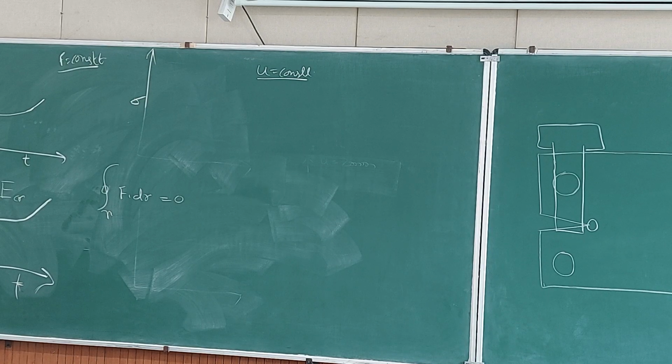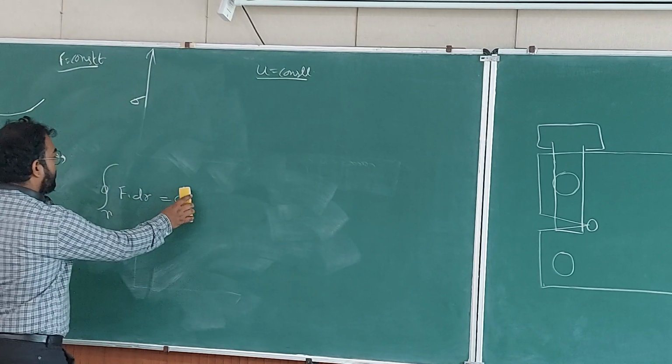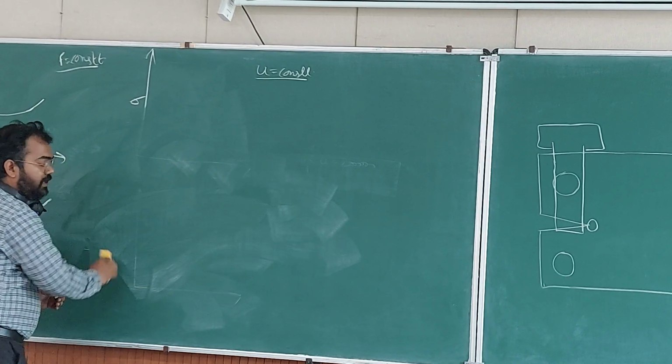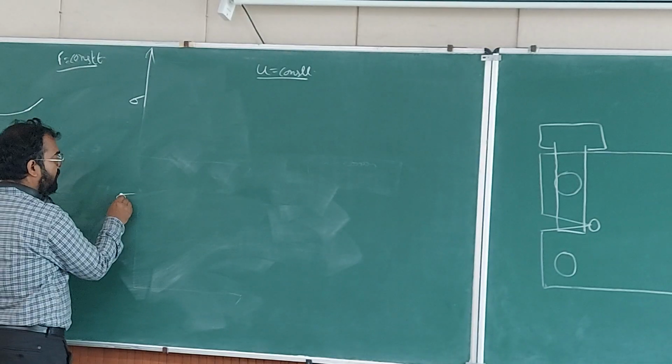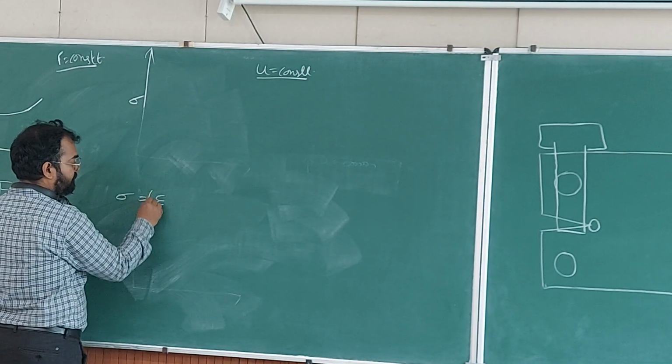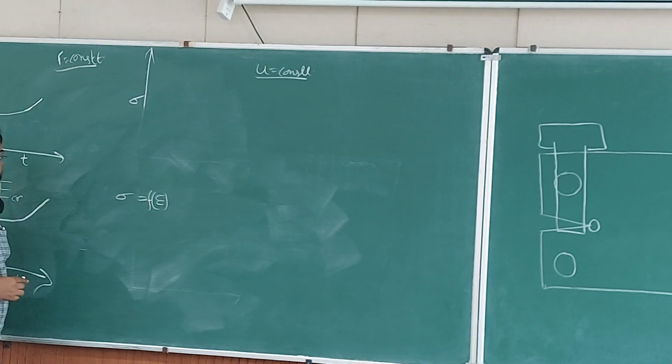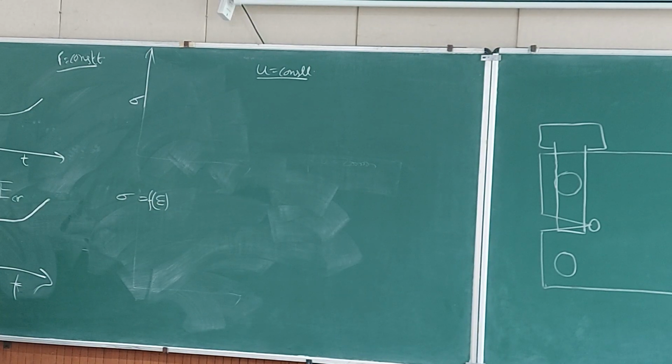So then it makes it a conservative field, meaning that this has to be a single-valued function of r. In our J integral, stress and strain are two variables, and stress has to be a single-valued function of strain. If this is true, then you apply the line integral and J is path independent.